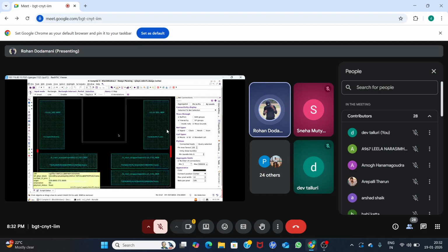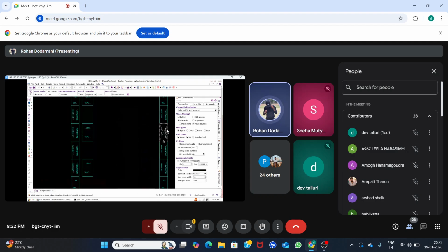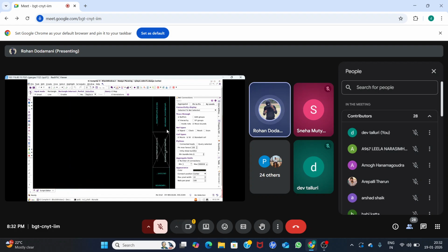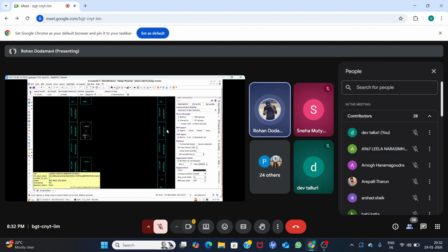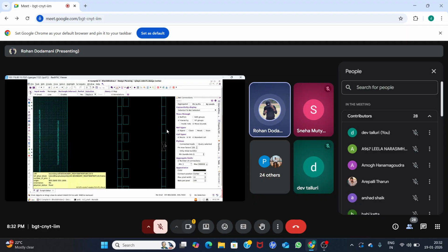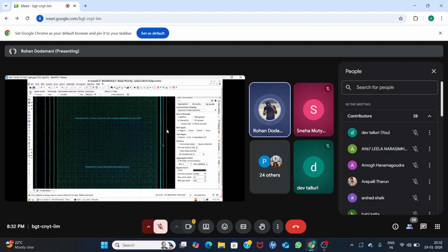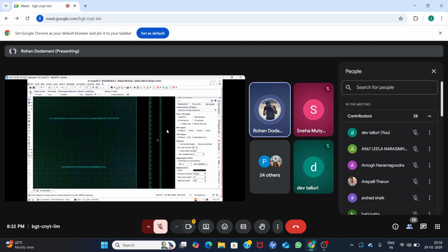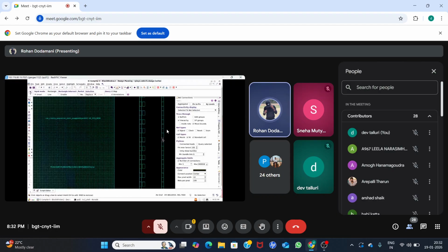And you can see the boundary cells also. At the boundary side, we are placing some boundary cells. You can see this one. So these are the boundary cells. They are already named also; you can see the naming is there: left boundary, right boundary, and even the tap cells are named tap. So these are the tap cells, and these are the boundary cells. Boundary cells will be placed only at the edge of the core boundary, right and left. It depends upon the project. If they give boundary cells on top and bottom also, we need to place them. But in our project, we have only right and left. So that is why I placed them.